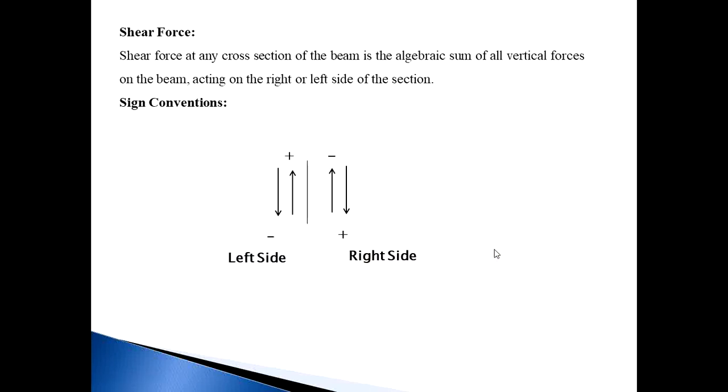So basically, shear force and bending moment are required for the design of a beam. Using shear force and bending moment, we can provide steel on the tension side or the compression side, and using the shear force we can provide shear reinforcement in the beam. So let us see what is meant by shear force.